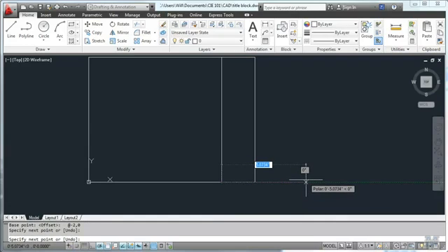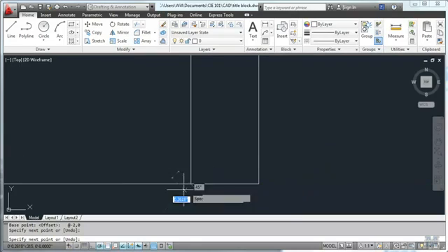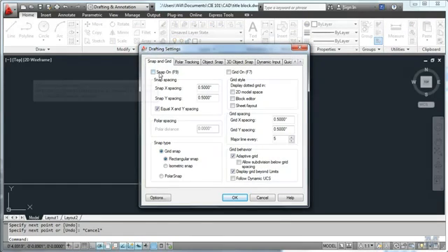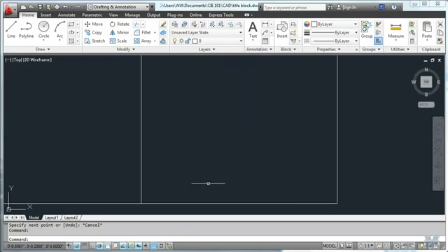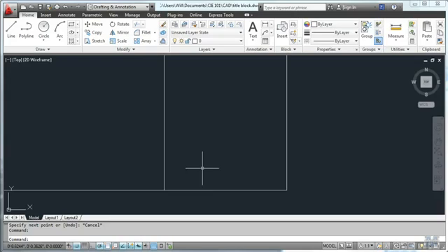That's where my 0.05 thing comes in handy, which I didn't mention yet, but here it is. Right click, settings on the grid, and let's turn this snap on and make it 0.05 inches. That way my cursor will only go to the nearest 0.05 inches. That'll make it a little bit easier to snap into the right orientation and not get too fussy about the geometry of this.